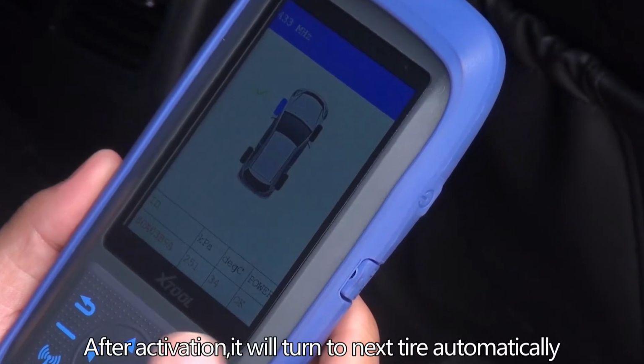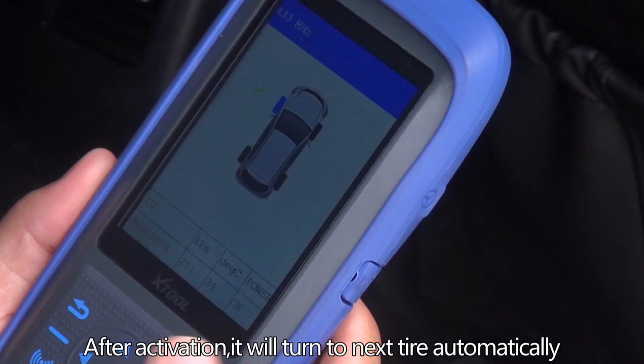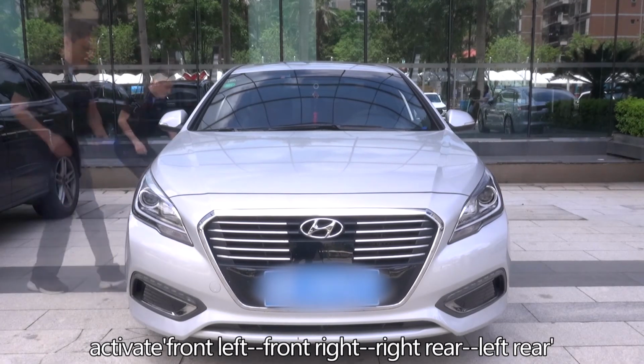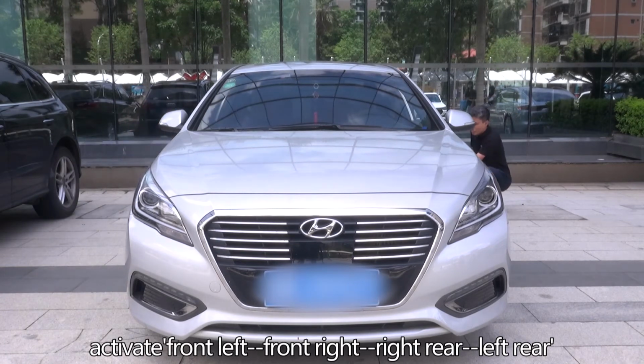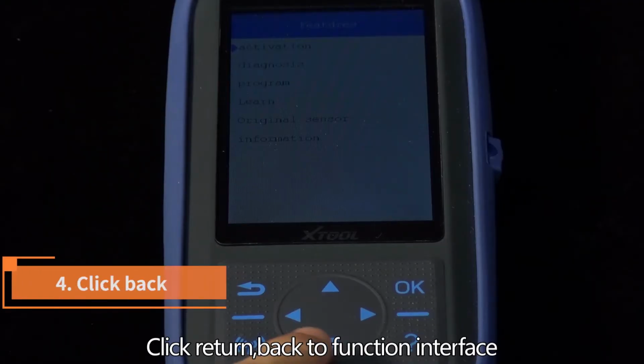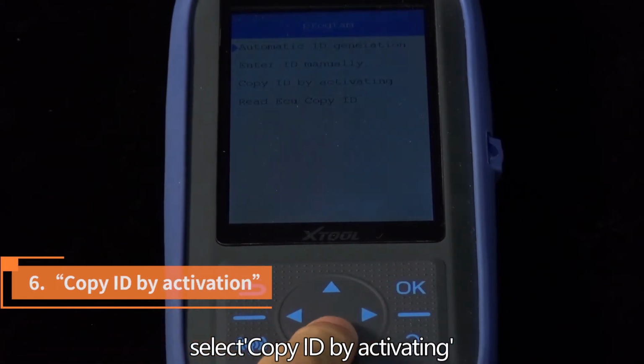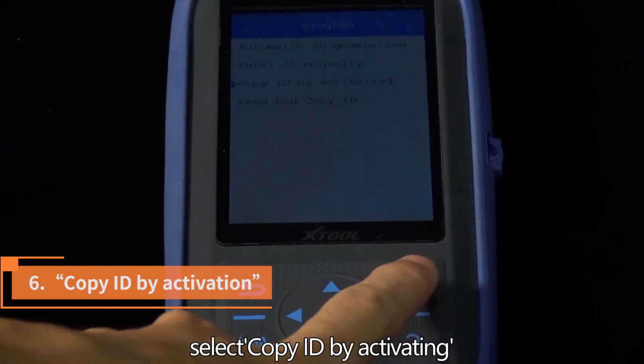After activation, it will turn to the next tire automatically. Activate front left, front right, right rear, left rear. Click Return to go back to the function interface. Select Programming. Select Copy ID by activating.